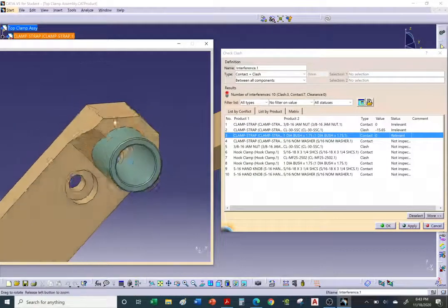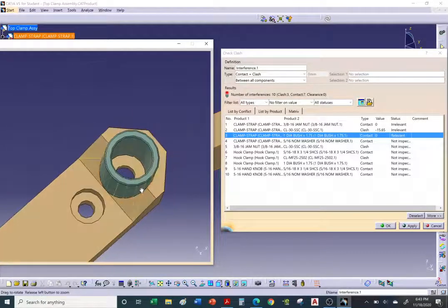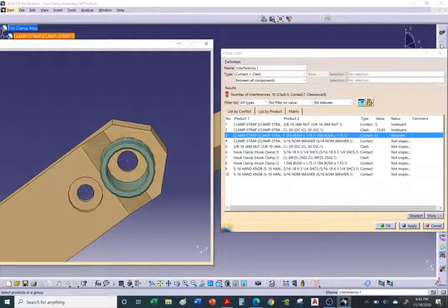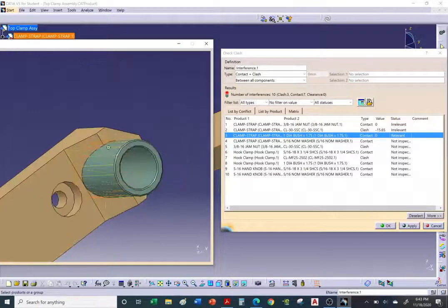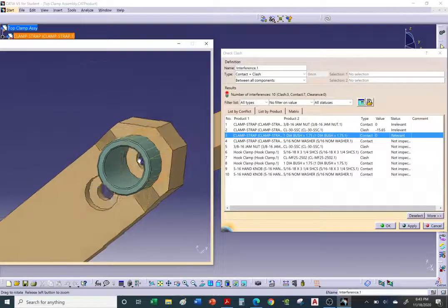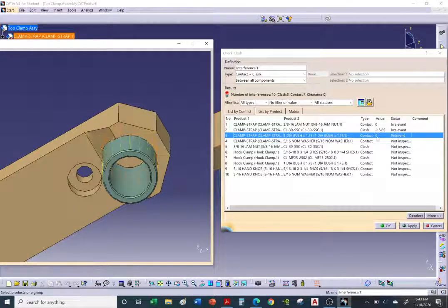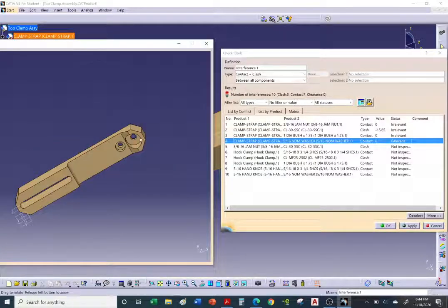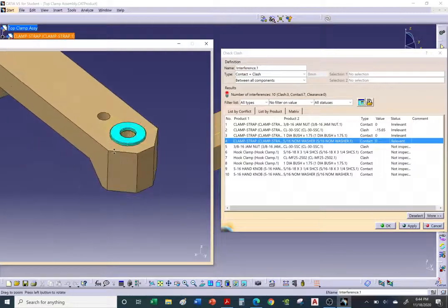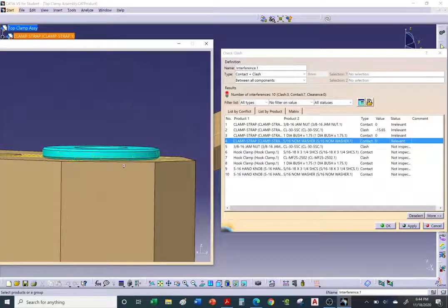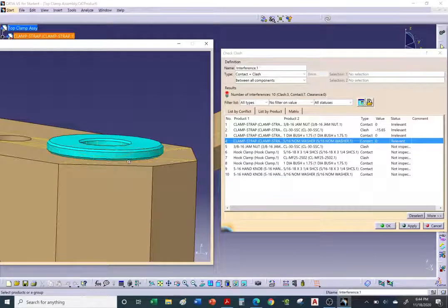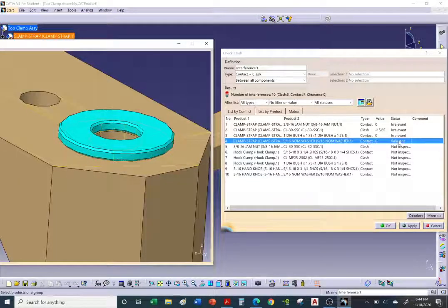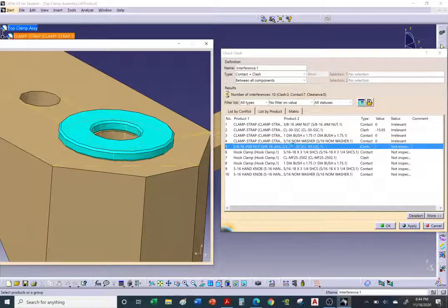So here we have a sleeve or a plain bushing, which slides into this counterbore hole, and it's making contact, right? So it's making face-to-face contact, and that's not an issue. So we can just go to the third issue and say irrelevant. Okay, move on to item 4. Let's take a look at the next issue. Hey, this washer is making contact. So it's just face-to-face contact between these two items. So we can go ahead and say, hey, yeah, we see the red light over here on the left. Click, make it irrelevant. No issue, not a problem. Let's go on to the next issue.